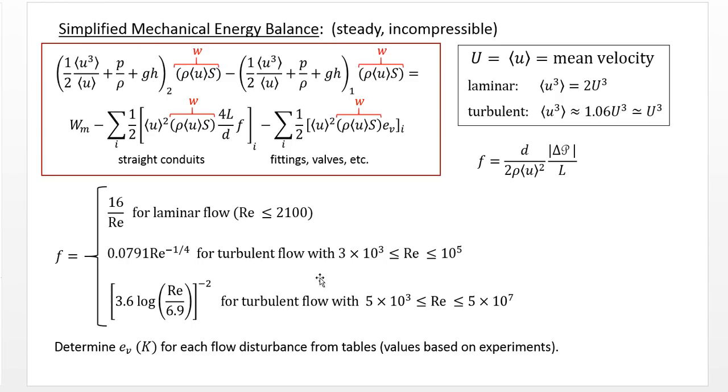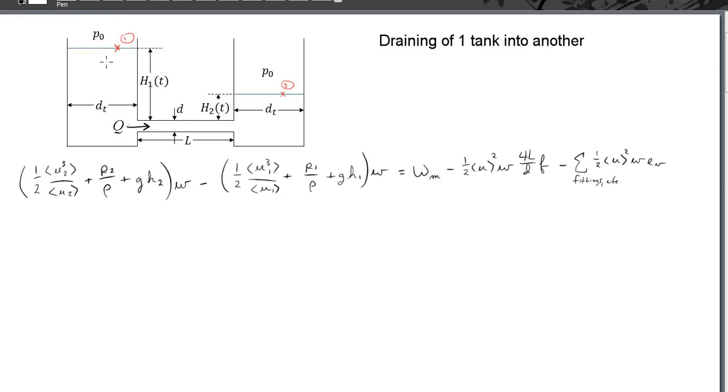So we need some actual data to figure out if we can use the Blasius formula or this other formula with the logarithm listed here, depending on the range of Reynolds numbers we're considering. Then eventually, once the liquid levels are close enough in height, the flow will transition from turbulent to laminar. And so we'd have to switch and use a correlation for laminar flow at that point.